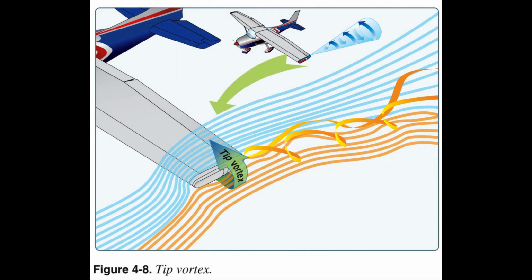A third dimension. To this point, the discussion has centered on the flow across the upper and lower surfaces of an airfoil. While most of the lift is produced by these two dimensions, a third dimension, the tip of the airfoil, also has an aerodynamic effect. The high-pressure area on the bottom of an airfoil pushes around the tip to the low-pressure area on the top. Figure 4.8.